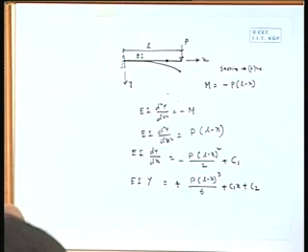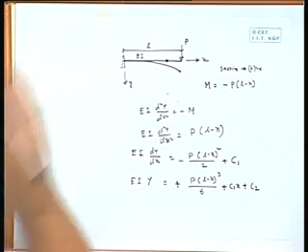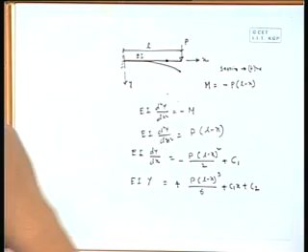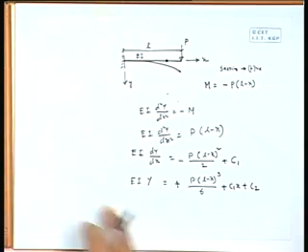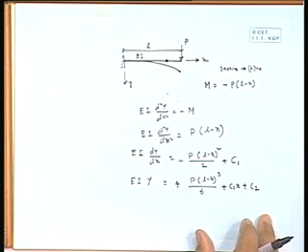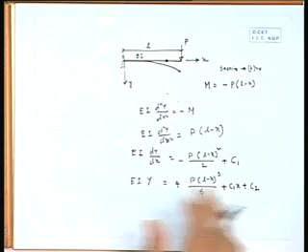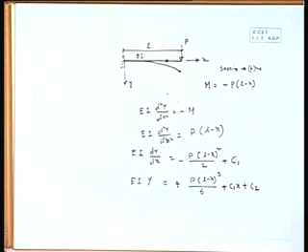Okay. So, integration of the differential equation already obtained. In the first integration we got the first derivative from the second derivative, and in the second level, without the derivative, we got y directly. So, the last line is the expression for y deflection, the previous line is the slope, and the one before that is basically the curvature relationship.